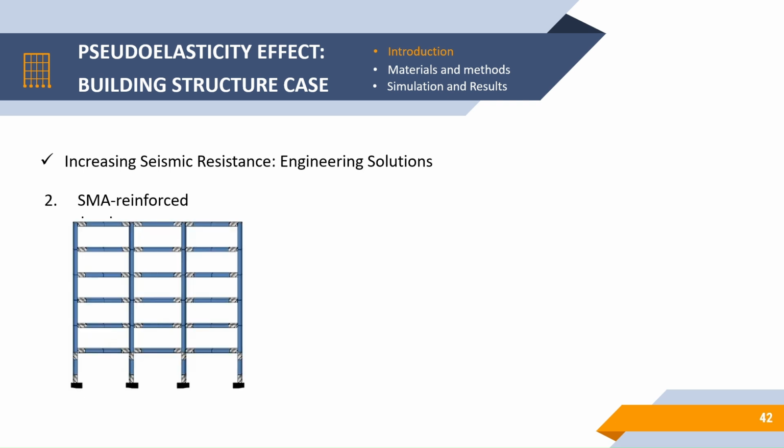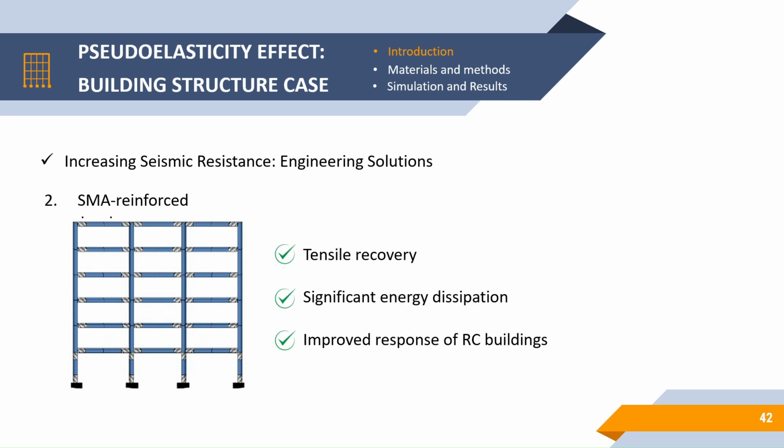The second technique is based on shape memory alloy reinforcements, which, unlike steel, provide strain recovery when unloaded during earthquakes. They offer significant energy dissipation, and they are quite effective in improving the response of reinforced concrete buildings.